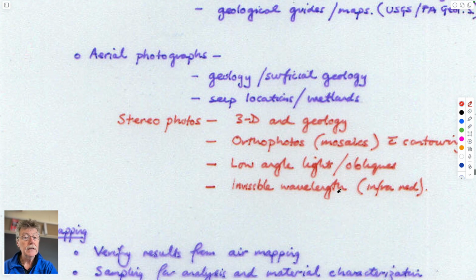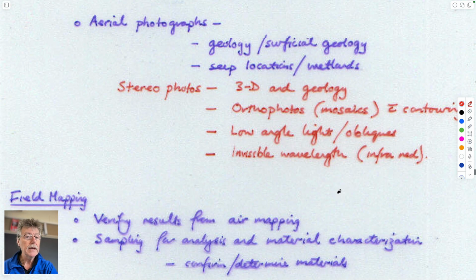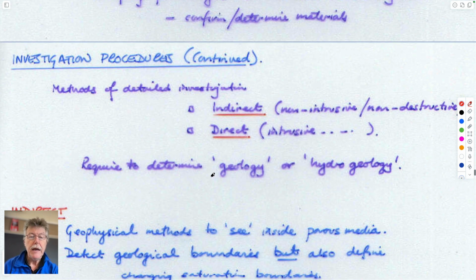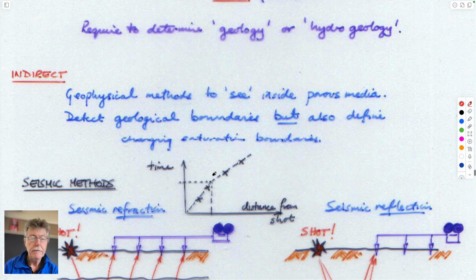With Google Earth, you can take aerial photographs or have aerial photographs available. Again, they only tell you something about the geology, not anything very specific, but it might give you some information about where you might look and drill holes. For instance, it might locate where there were springs that were seeping and you could sample and get some information from that. And field mapping would be walkovers.